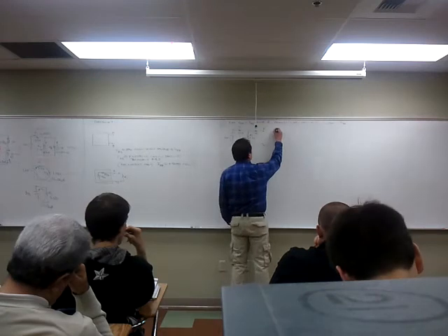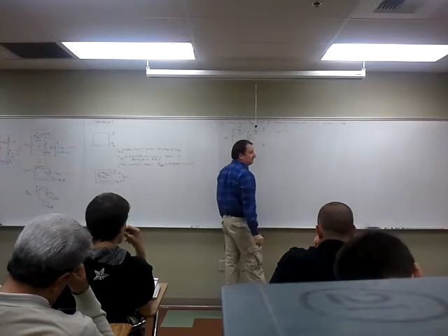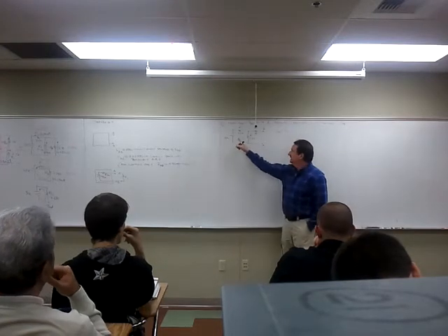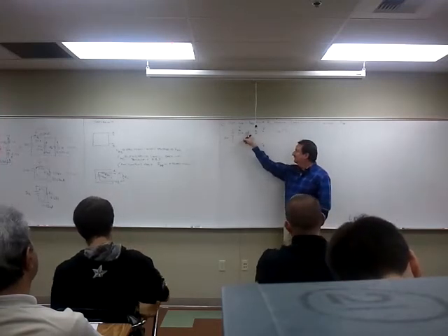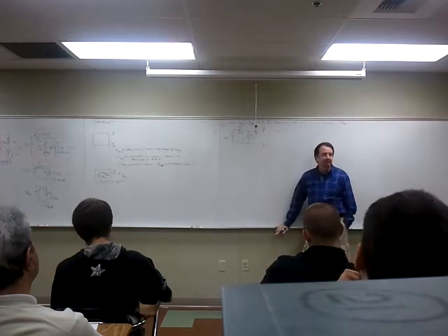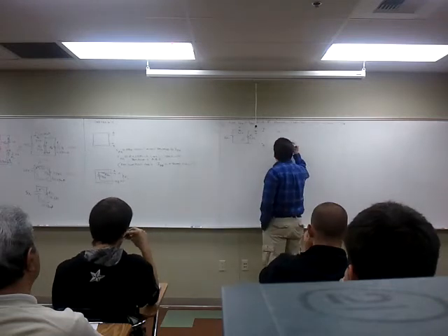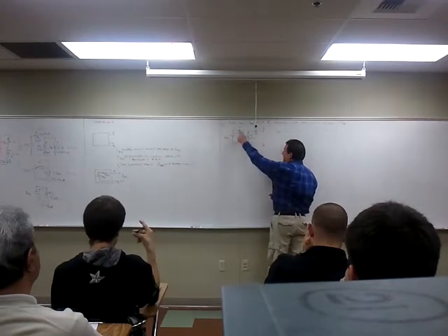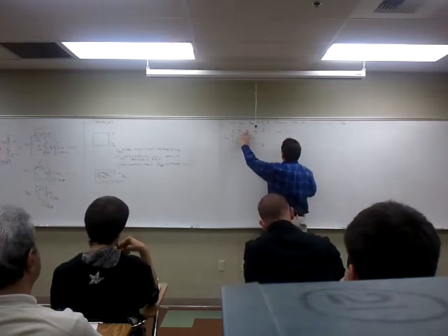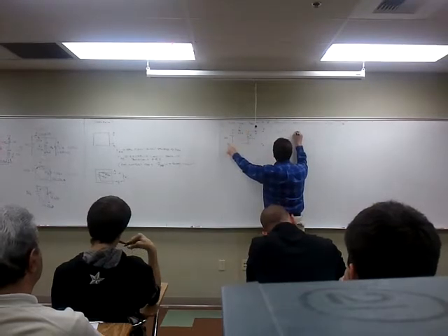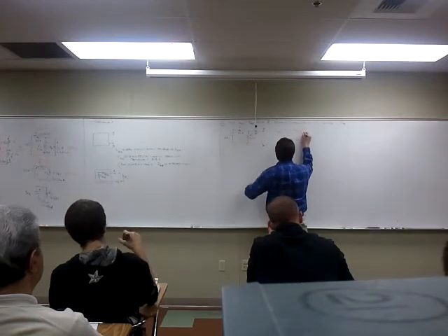Therefore, isn't the voltage from A to B the same as the voltage drop across resistor 2? Because any current that leaves the source only flows through R2 and R1, establishing a voltage drop across R2. And what do we have going out to terminals A and B? V2, correct? So V2 can be found by the voltage divider. Aren't those two resistors in series? So using a voltage divider, I can find V2 by taking the total voltage, V total, times that resistor, R2, over the sum of R1 plus R2. That's the voltage divider equation.